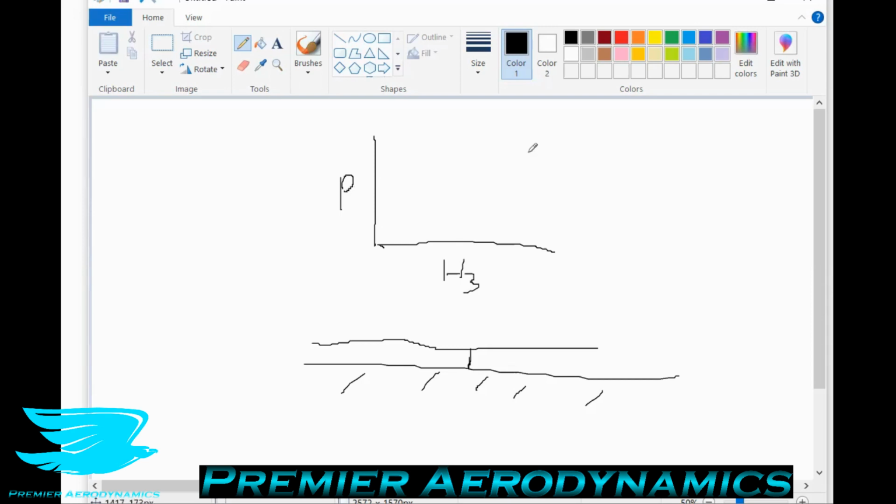You'll find that when it's laminar, it will be a fairly low power spectrum. So the power will be quite low. As soon as it transitions to turbulent, it will be significantly higher, but also there will be some more jagged peaks around. So this is quite indicative of a turbulent boundary layer because obviously turbulence is quite random, which means that there is a lot of unsteadiness at all different frequencies.